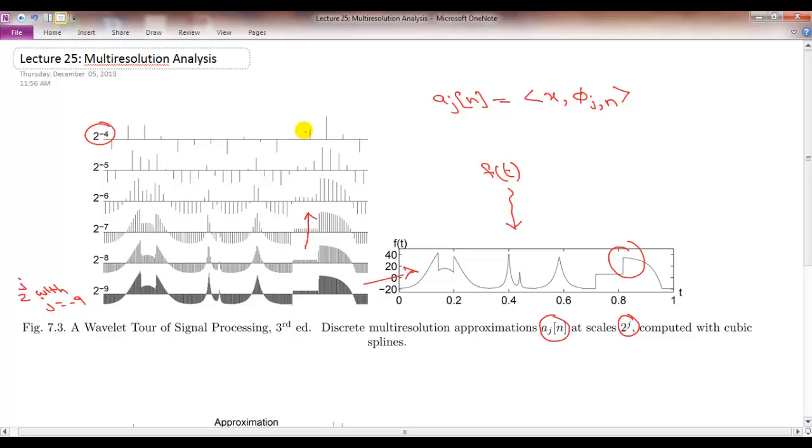And if someone says, well, I now have more bandwidth available, then you just go to a different scale. You go to a finer subspace, and effectively you have not lost anything. You still have some sense of what was being transmitted, you just don't get the fine details. Okay, so that's the basic principle behind multi-resolution analysis. You are getting a coarser view as your j gets large, and you get finer details as your j gets small. And if your j gets too small, you almost get back to your original signal.